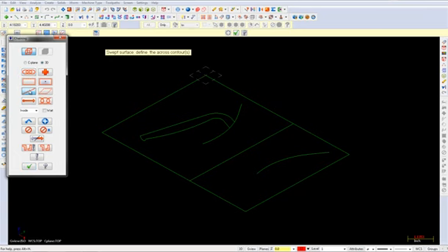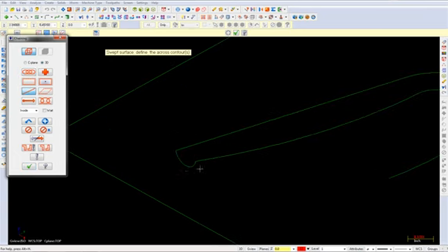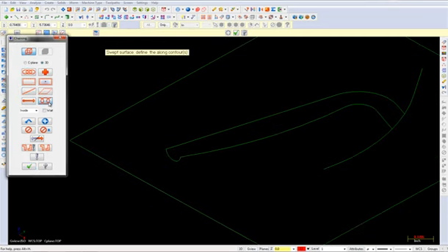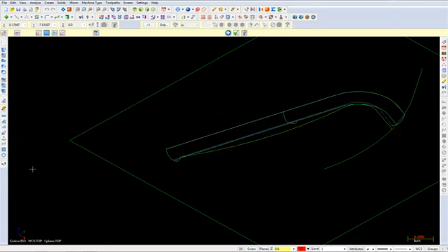Enable Single in the chaining dialog box and chain this arc in this direction as shown. Then select the OK button. Enable Partial in the chaining dialog box, select this line and then this line here, and then select this line and this line here. Select the OK button to generate the surface.